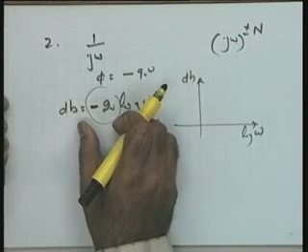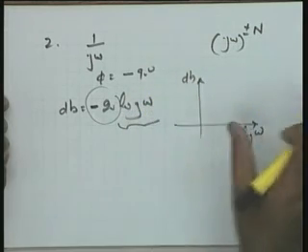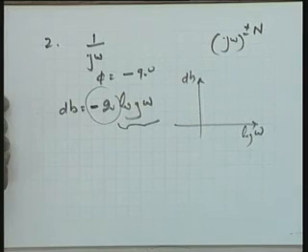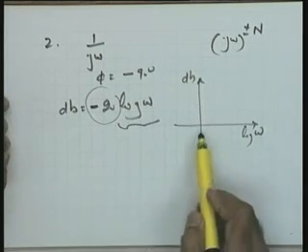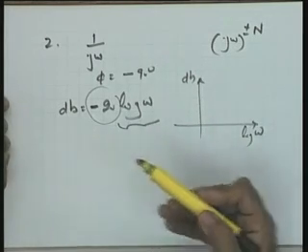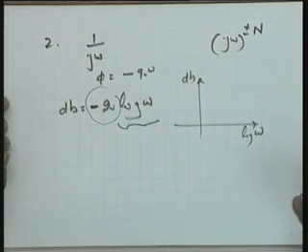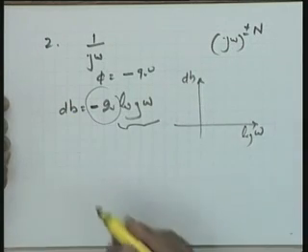Minus 20 dBs per unit of log omega. Okay. Now, as I told you yesterday, it is this contribution from Bode which makes the construction of the frequency response plots very simple. This total plot becomes simply a straight line of minus 20 dBs per unit of log omega. Now what is a unit of log omega?